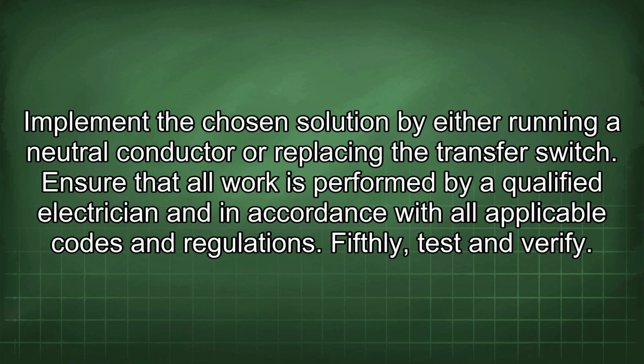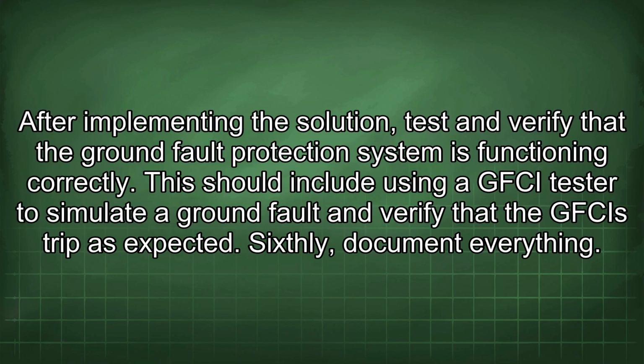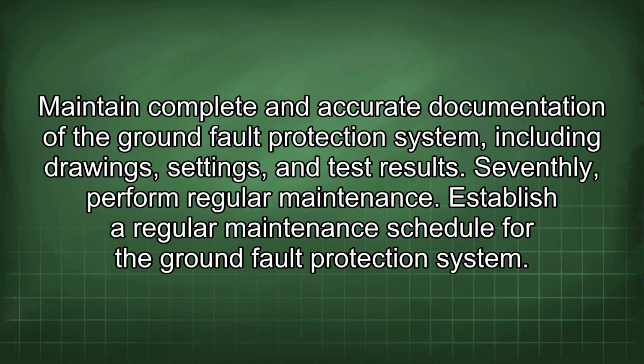Ensure that all work is performed by a qualified electrician and in accordance with all applicable codes and regulations. Fifthly, test and verify. After implementing the solution, test and verify that the ground fault protection system is functioning correctly. This should include using a GFCI tester to simulate a ground fault and verify that the GFCI is tripped as expected.